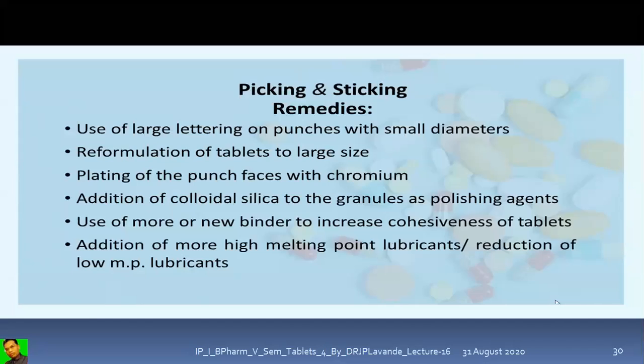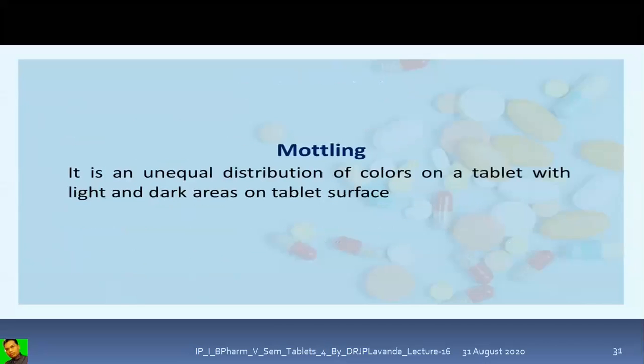Use of more or new binder to increase the cohesiveness of tablets. Addition of more high melting point lubricants, reduction of the low melting point lubricant. So all these are the remedies by which we can avoid the process of picking and sticking.